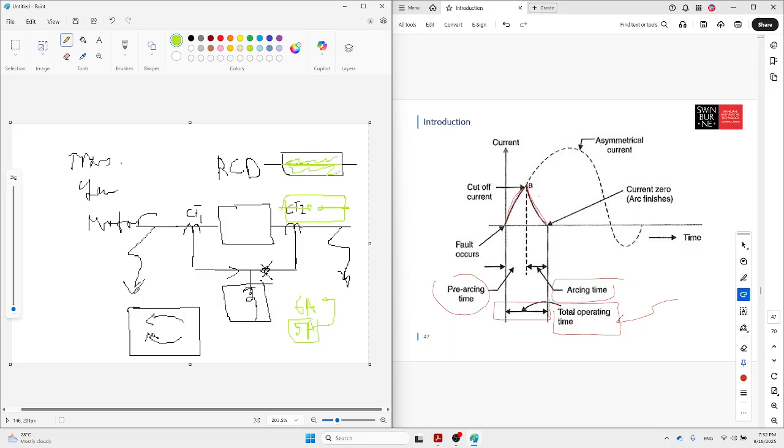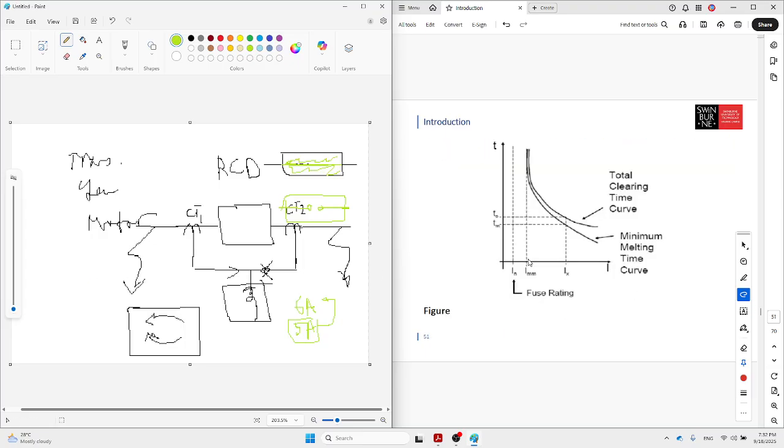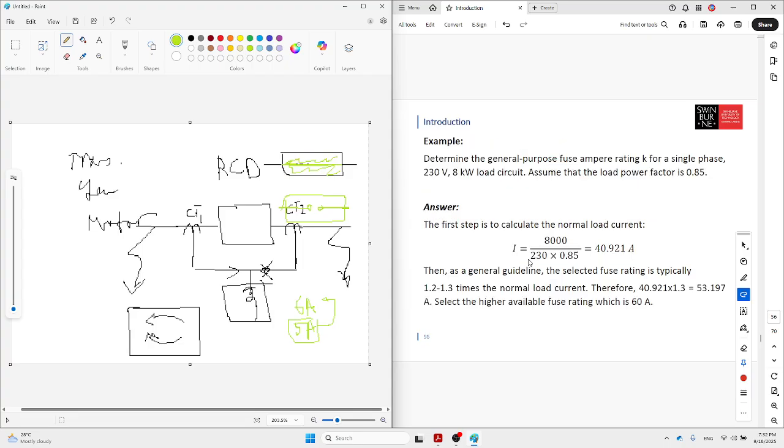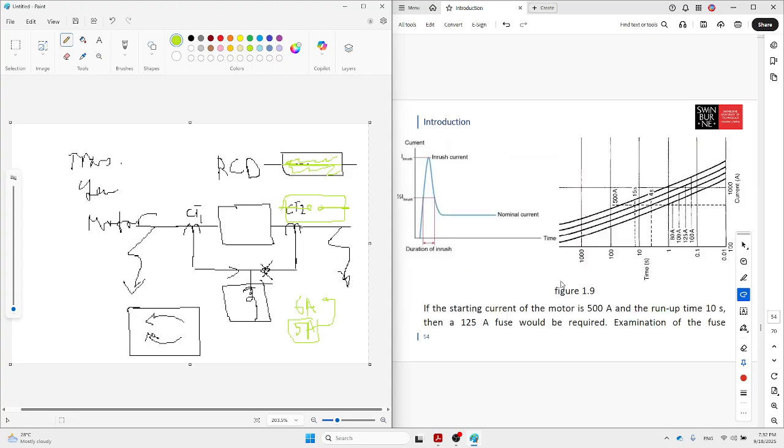What's the meaning of best current close to operating current? For fuses, there are standard classes available in the market. You cannot go into the market and say, okay, the current of my device is 5 amp, so I'm searching for a 5 amp fuse. No, in the market, I think the list of that one was given by me somewhere. If it's not, I will provide it